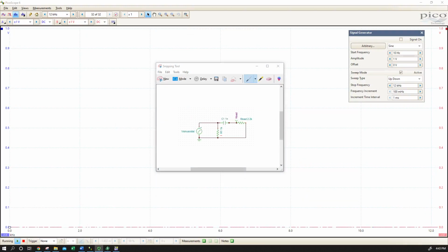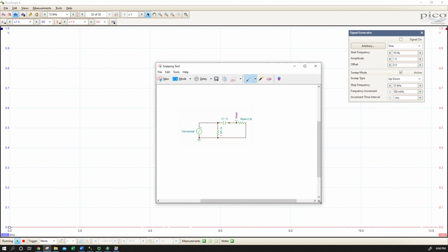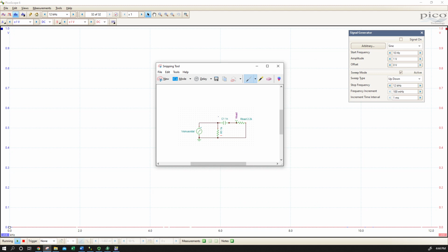Okay, now that we've looked at the behavior of an inductor basically as a voltage divider creating a low pass filter to a load resistor in series with it in its own branch, we're going to look at what happens if we switch that inductor with a capacitor in the exact same configuration. So I'm displaying, I can't scale it up. I'm displaying basically an equivalent circuit in a schematic here.